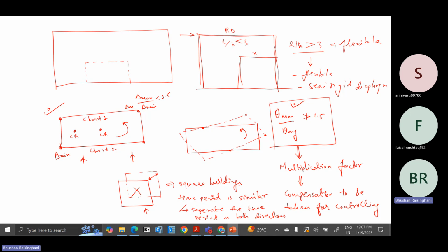So they increase the rigidity in the core and perimeter, and they distribute the stiffness in such a manner that it will not have modal coupling, right? So this arrangement has to be planned by a structural engineer, how it is behaving and in what manner.